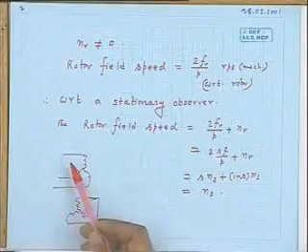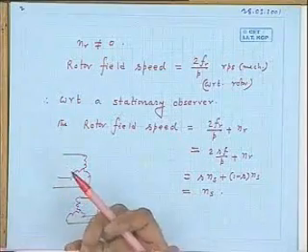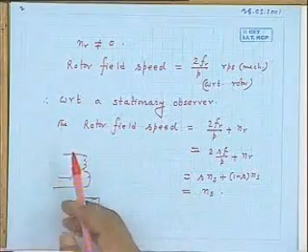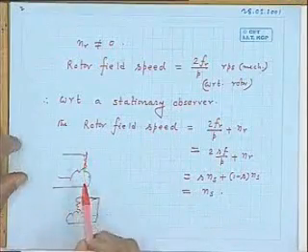That is very important. And it can nicely do that, because the stator can only draw 50 Hertz power. By drawing 50 Hertz current in its circuit from the supply, it too can produce a rotating field moving with NS, and therefore it is always able to cancel that out, no matter what the speed of the rotor is. This must be borne in mind. You should understand this point. No matter what the rotor speed is, the stator winding will always see the rotor field moving.